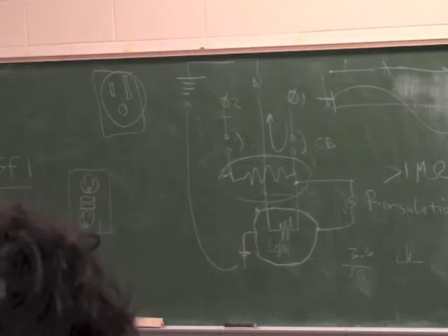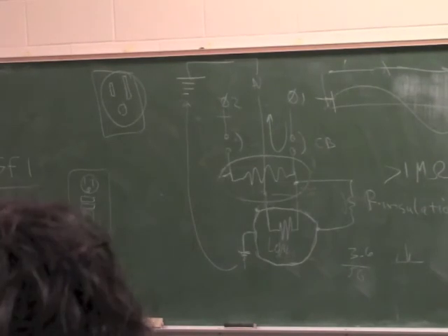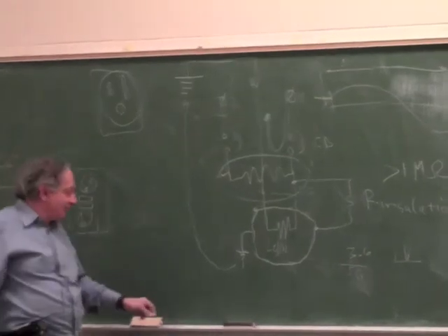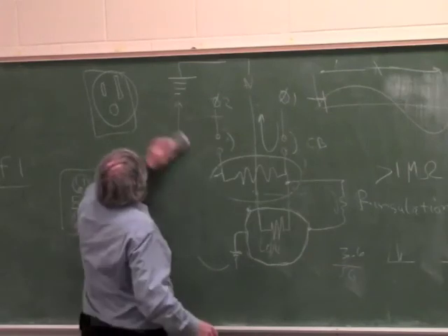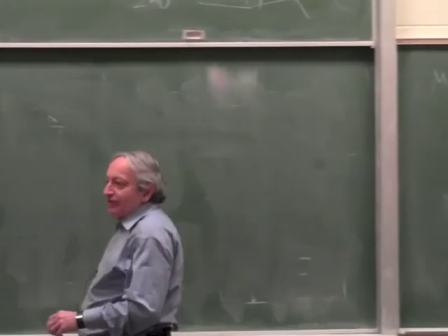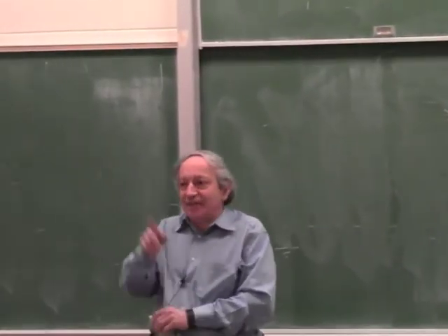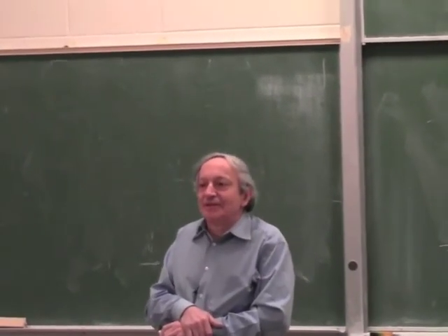You buy it for $10 in any hardware store. How does this work? How does this know you're getting electrocuted? So if you listen carefully, a minute to think about it, you should be able to explain how it works. So, how does a GFI switch work? Yes? It ensures that the current going to the neutral and live are the same.